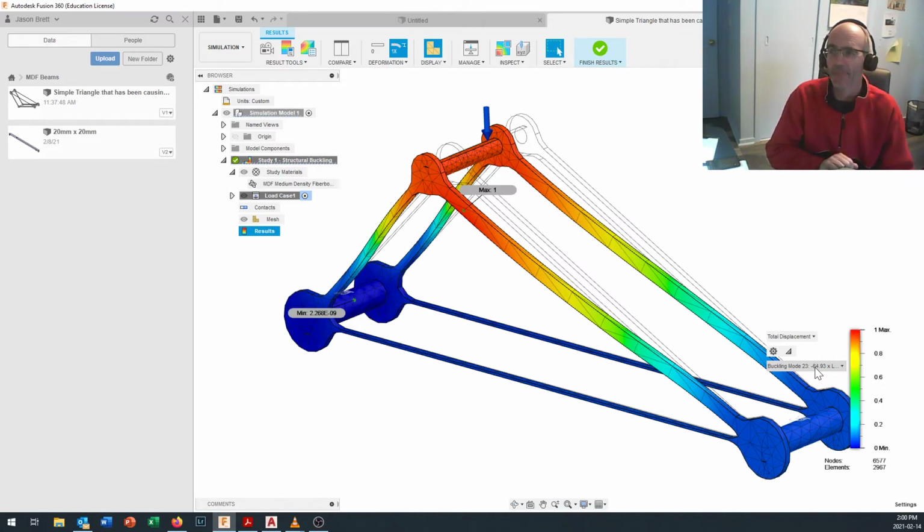What we observed in the lab was that it buckled at 68 and 69 newtons. This was predicting a 65 Newton failure. That's accurate to within a few percent of what we actually saw, and just a hair conservative. It's a beautiful engineering calculation. Now, when I was a student at BCIT, doing a calculation like this was probably PhD level work. At that time, simply developing the mesh and getting a meaningful mesh was a lot of work. Setting in the load conditions and all that, and then interpreting the results was really, really hard, difficult to do.